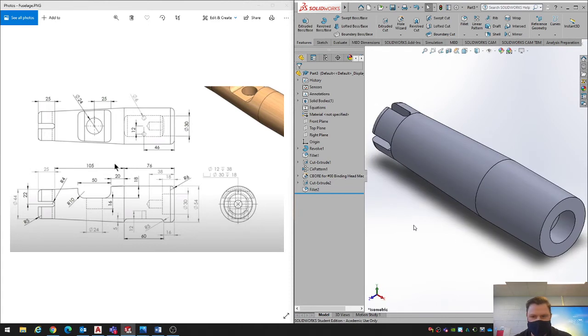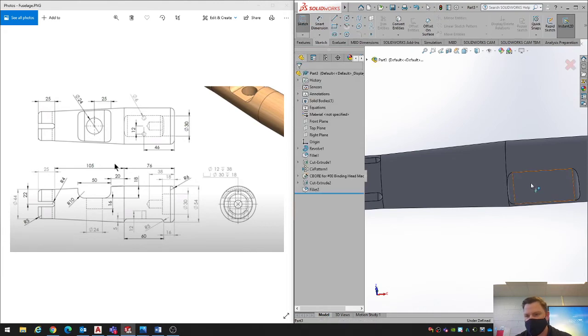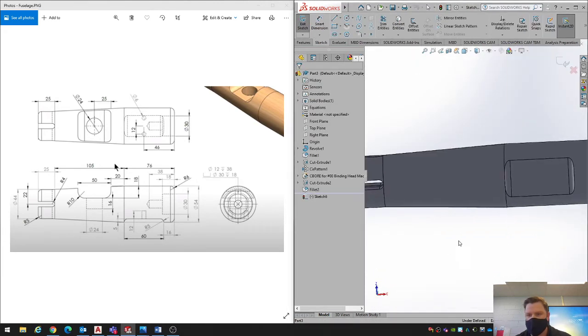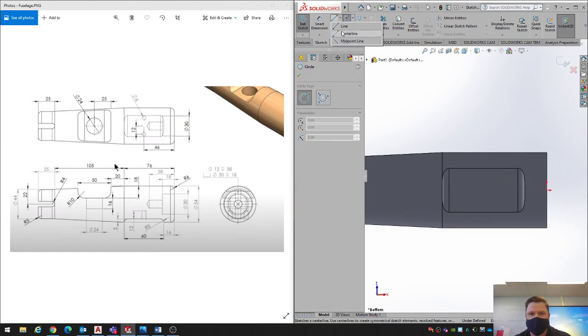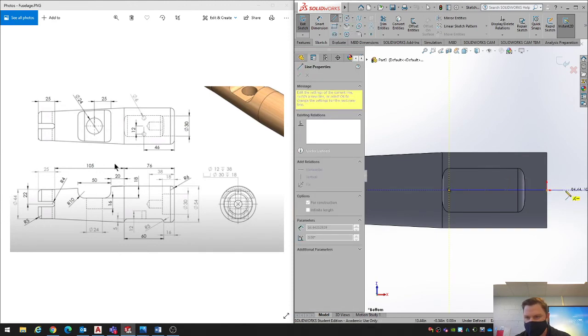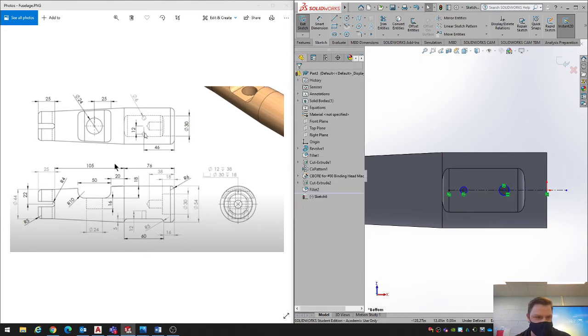And I've got a little circle. Actually, this is 2 circles, here and here, that protrude up a little bit. So I'm going to sketch on this face. Let's see here. I'll draw a center line going down the middle. I don't know if I need it, but we'll see. And then I'll make 2 circles. Go ahead and set the sizes of those. Sorry, that's the wrong direction.